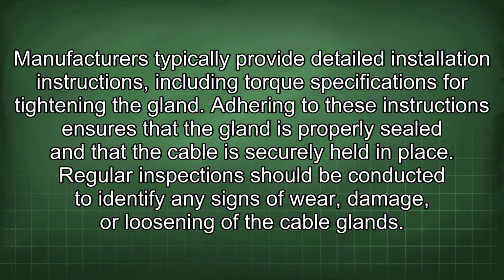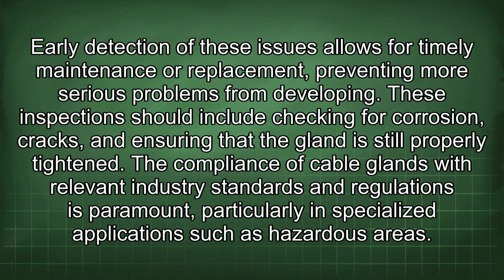Regular inspections should be conducted to identify any signs of wear, damage, or loosening of the cable glands. Early detection of these issues allows for timely maintenance or replacement, preventing more serious problems from developing. These inspections should include checking for corrosion, cracks, and ensuring that the gland is still properly tightened.